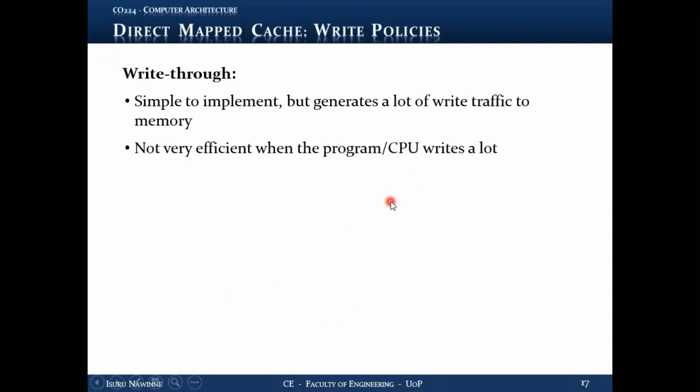So the issue is it generates a lot of write traffic to the memory. Every time you have a write access, you go to the memory anyway. As we know, memory takes several CPU clock cycles. It takes a long time to read, and it can take a long time to update as well. Usually the read time is the longer one, but writing can also be slow, several clock cycles.